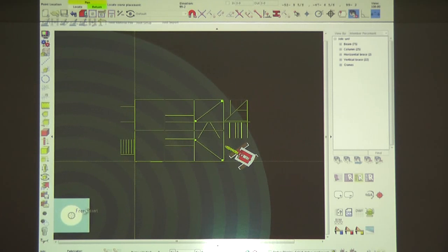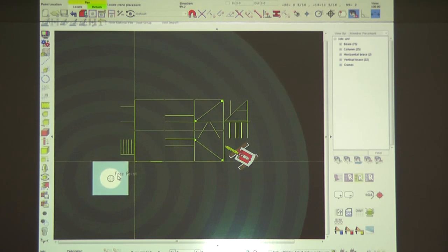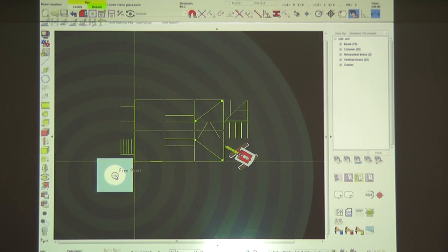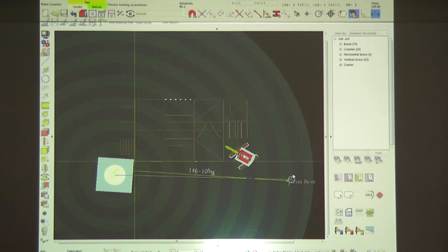Well, probably getting too big of a crane then, right? But the point is, this tool can help the erector decide what crane they could use or need to use. This is a tower crane, so there's a big concrete footing under it. We're going to position the footing so that it doesn't disturb any of the footings or walls of the current structure.